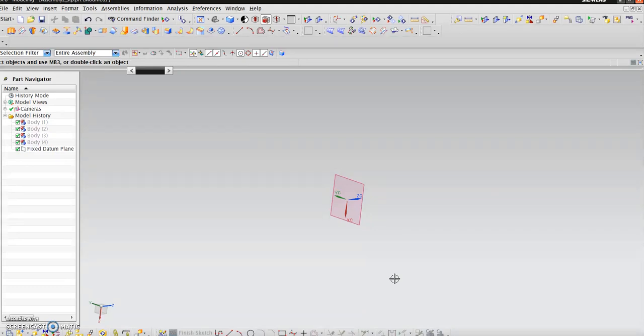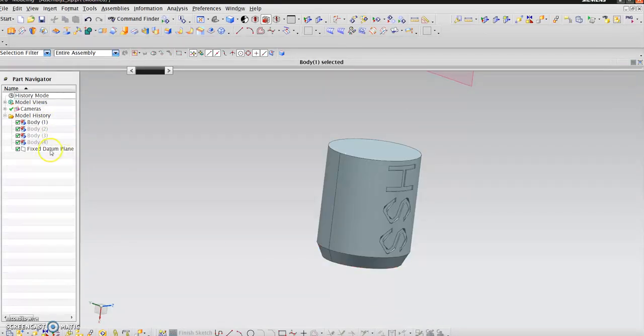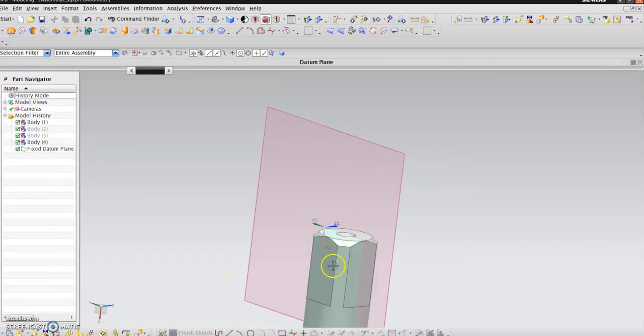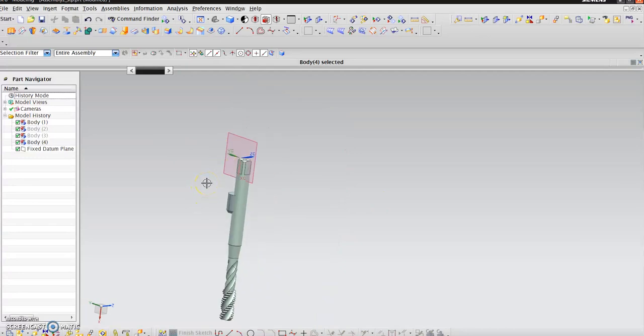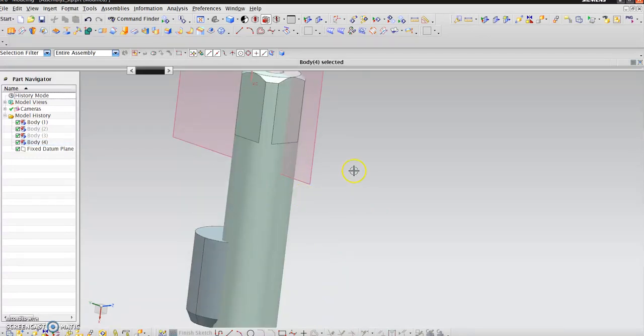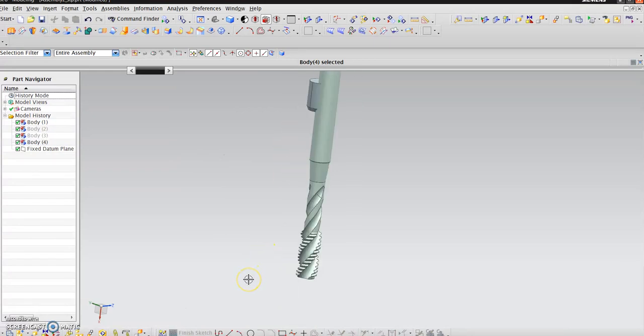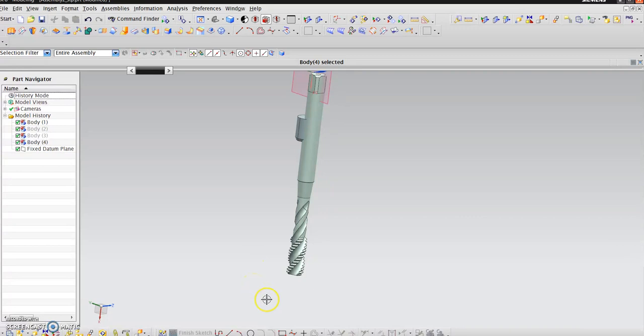And I will be able to explain to you why it's critical that during rigid tapping we need to have a holder that will locate the flat of the shank of the tap in the collar, so it's squarely located, and that gives a back support and is clamped in for rigid tapping, so that during the feed of the axis the spindle rotation will be synced with the feed rate of the tap itself.